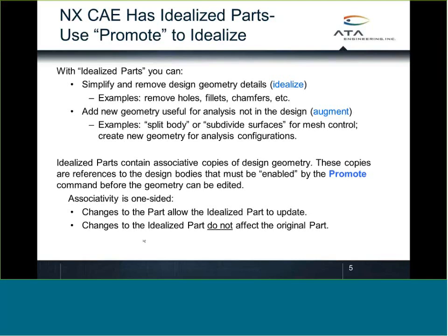Now the other thing I want to point out here is that the way the idealized part facilitates this kind of hierarchy is by creating an associative copy of the design geometry. As a consequence, when you're working with the idealized part, you have to enable revisions to that body through the promote command.